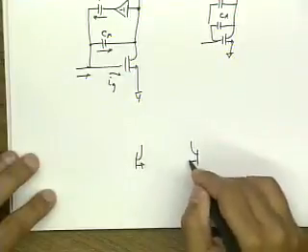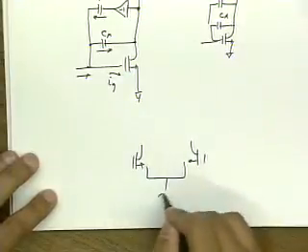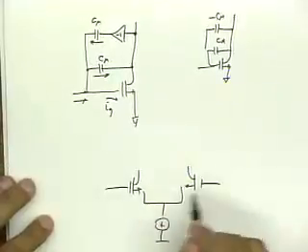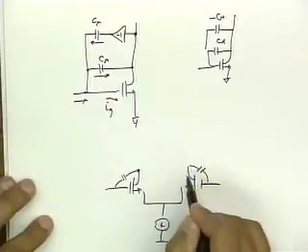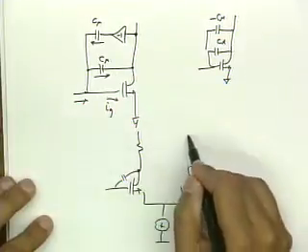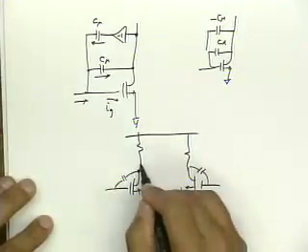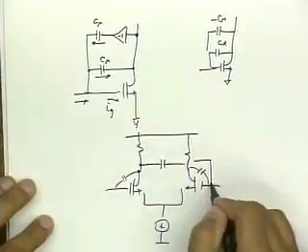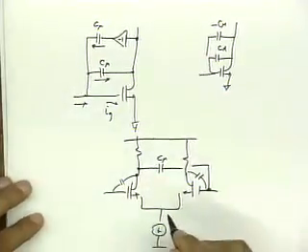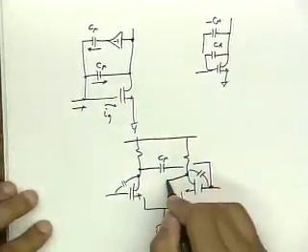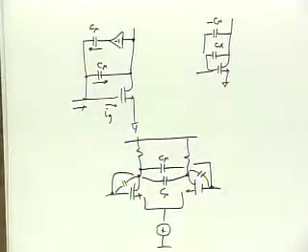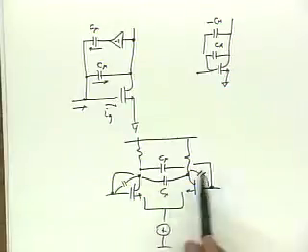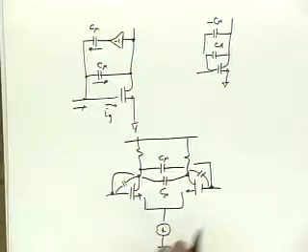Well, in integrated circuits, there's a really easy way to do this. You just cross-couple your devices. So if I have a differential pair, for instance, then automatically I have the output voltage and its inverse available to me. So I can take this node here and connect a fake C mu, if you like, and I can take this node here and generate another fake C mu and connect it into here. So this cross-coupling will provide unilateralization for this device, or neutralization.